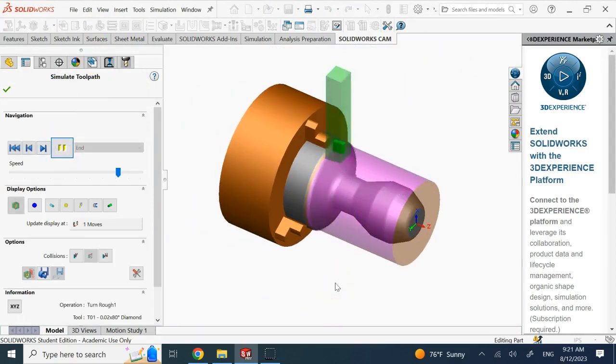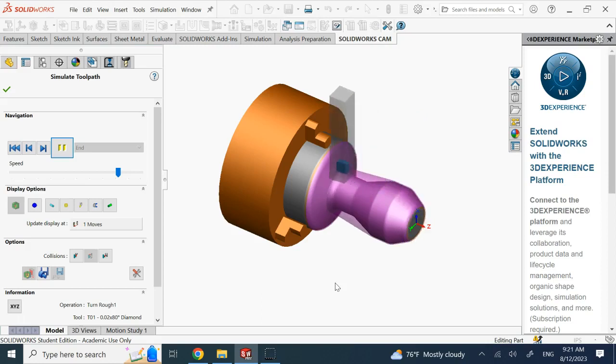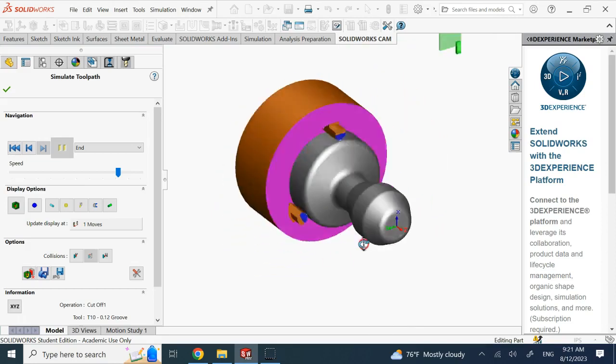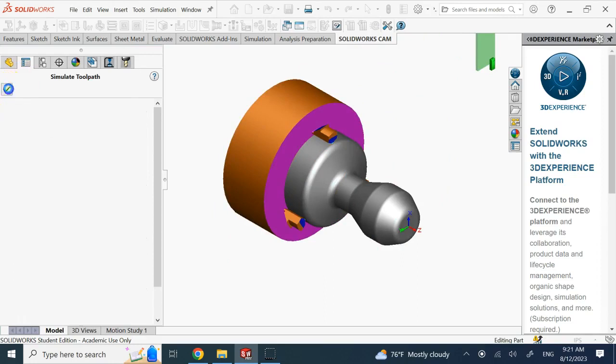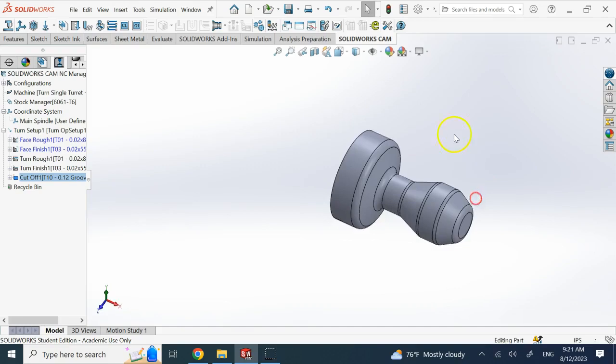Not every geometry that you create can necessarily be made, especially with machines that do not have a ton of axes. For those, you need to go to higher axis machines. So for a simple lathe, which is really a 2-axis machine, let's see if this time the profile can be done. There we go. Look, perfect, clean, nothing green is left. So this is very important for you to reconsider your designs.